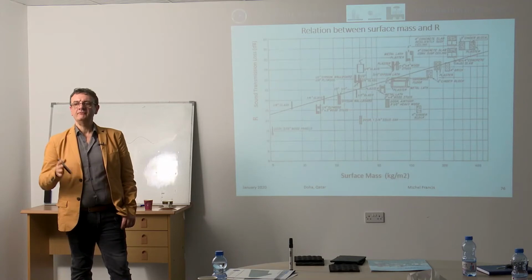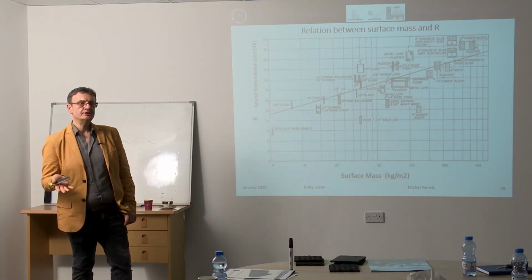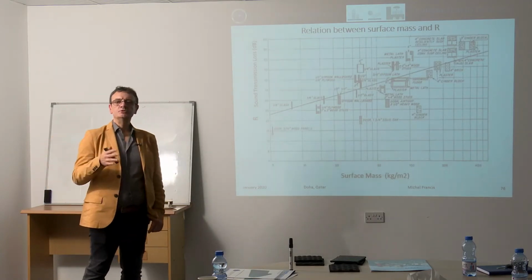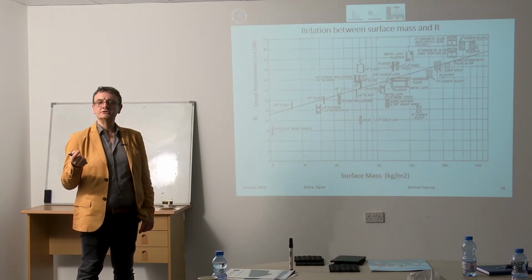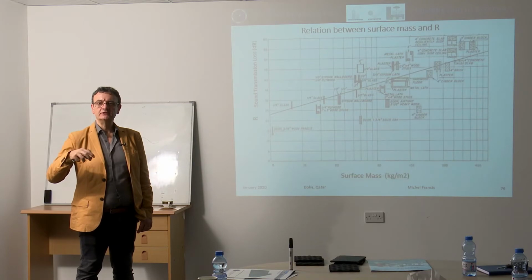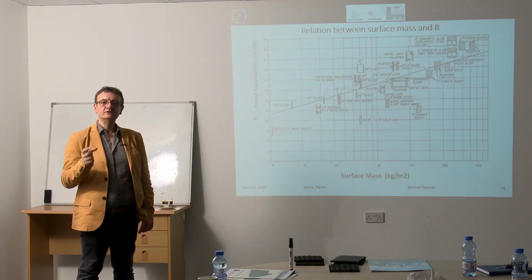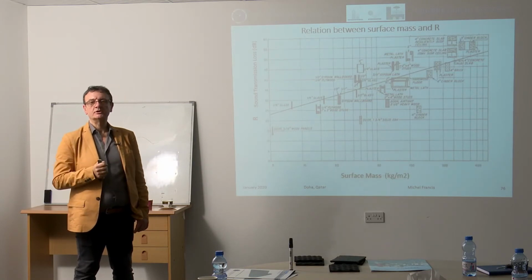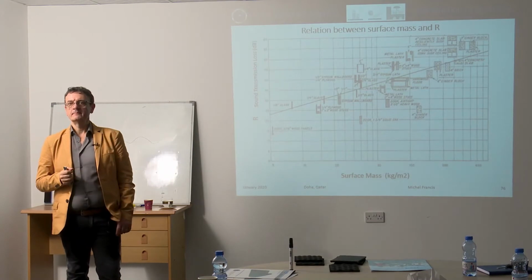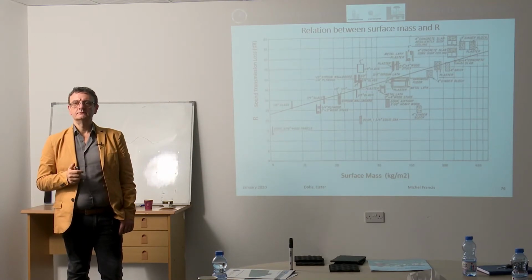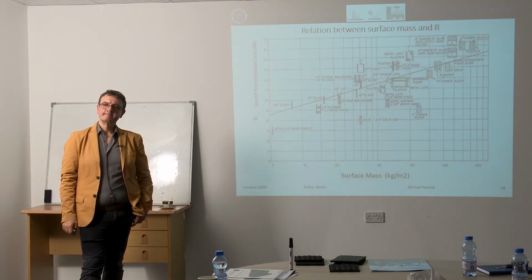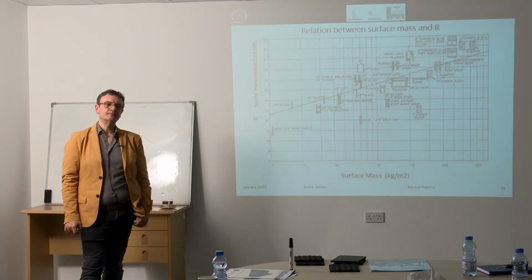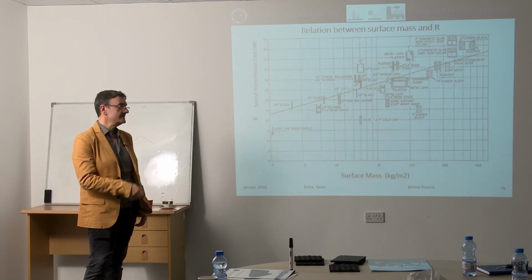This is why, when you have a block wall, masonry block or concrete, between two spaces and you want that block wall to be an acoustic partition, you must have it grout filled, or you must have solid block. So when the density of the material increases, STC will automatically be affected. It is related through the mass law.